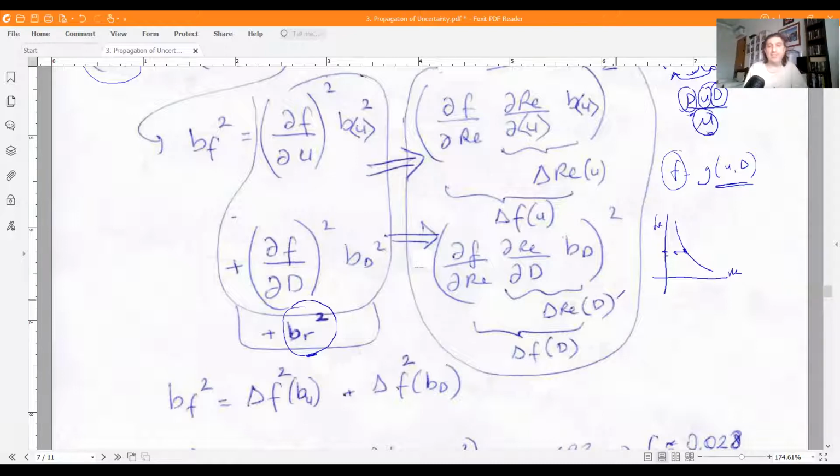And there is another thing actually also, but here I have omitted this one. This is also related with the smoothness of the pipe. This is not a single curve. I'm going to show it in a minute, I hope. But you should usually assume some E value for the smoothness of the pipe. So depending on the smoothness, we have these different curves here. So they are in a band actually, not a single curve like this. Therefore, you need to maybe include this factor also. For the time being, I haven't included it here because there is already too much detail. Now let me show you the figure.